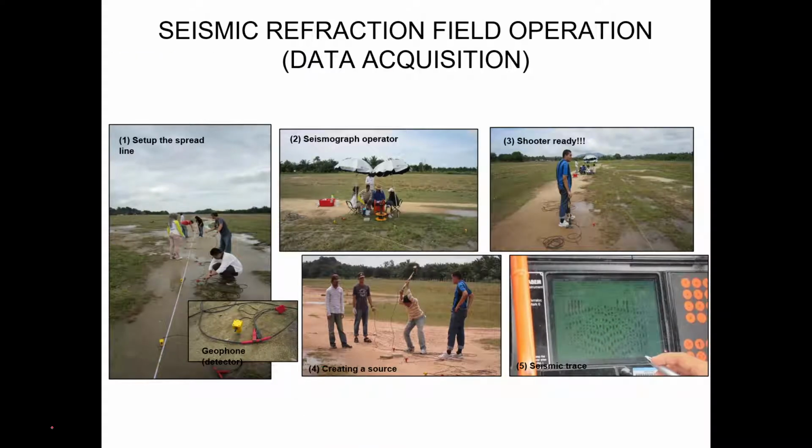Okay, this is the cable. Then this is the geophone, and this is how they look. This is the hammer and this is the strike plate. They hit the hammer on the strike plate to produce the seismic wave. And what you can see here, this is the center, the ABEM. So the operator, when they hit the ground, all the workers must stand still, stay at their places.